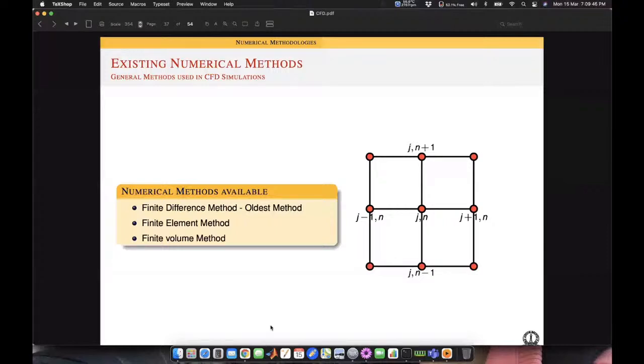In the finite element method, you connect the elements and interpolate the data between them. So the basic difference between the finite difference method and the finite element method is that in the finite difference method you solve only at that particular point. In the finite element method, you create an element between these 2 points, and you ask how to interpolate the data between those elements. So you create a structure, a polynomial, and you solve at those data points and interpolate the data.